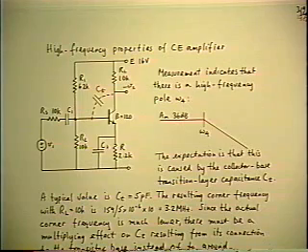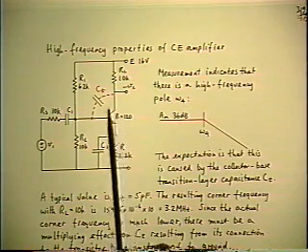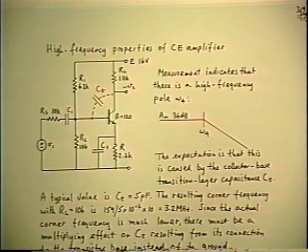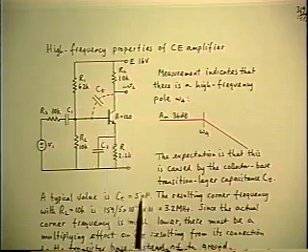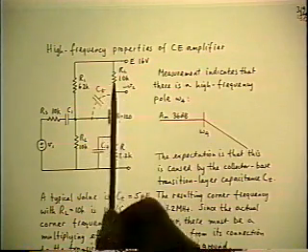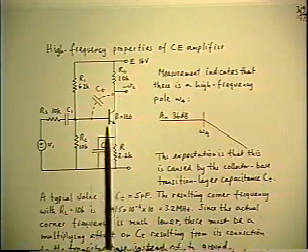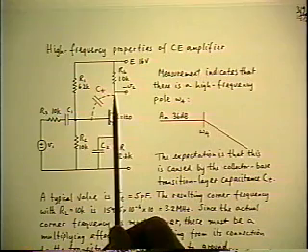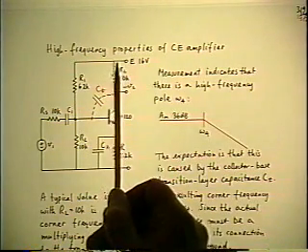So rather than dropping the idea and looking for some other cause, suppose you think a little more carefully about whether the CT really is behaving like that. Because the 3.2 megahertz is the corner that you would get if the CT were directly in parallel with the RL. But it isn't. Only one end is connected to the RL. The other end does not go to AC ground, as RL does.